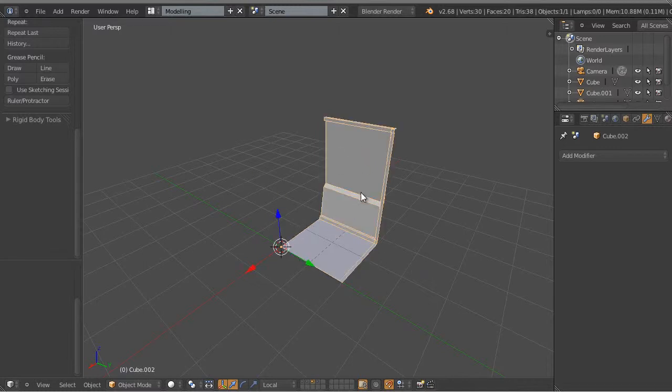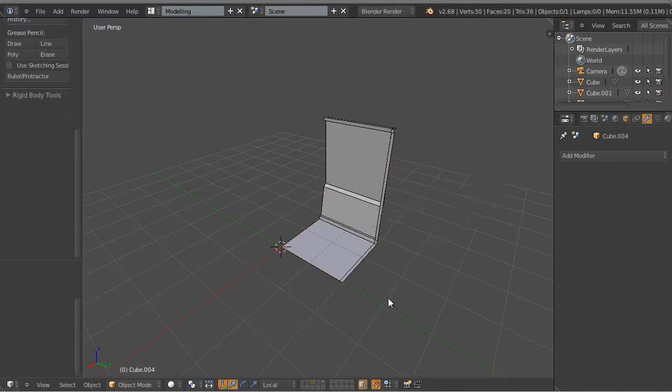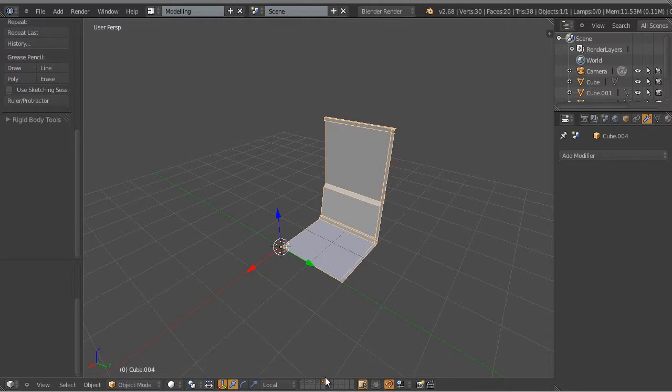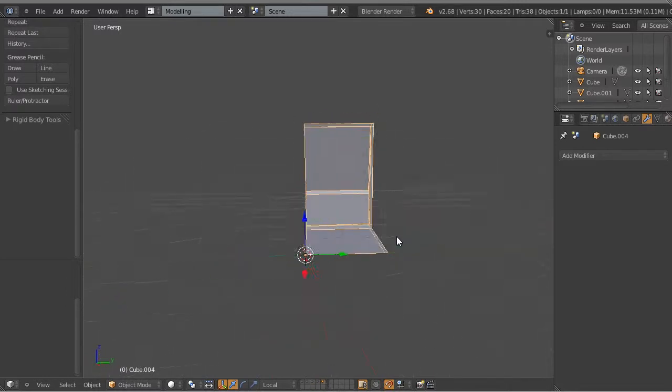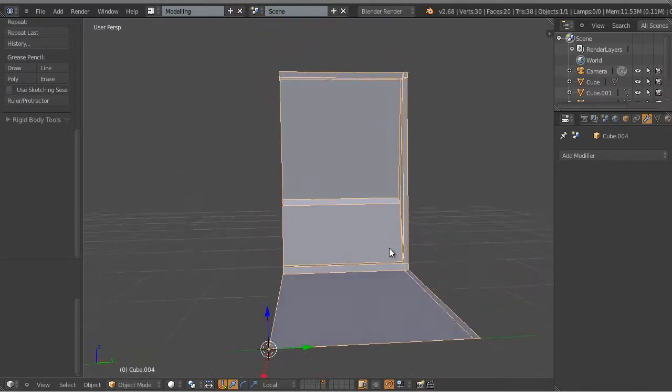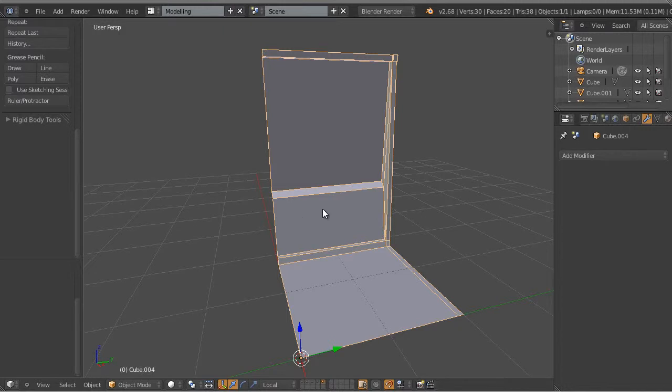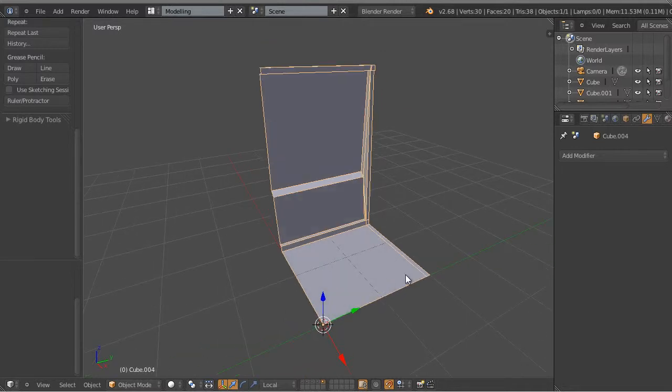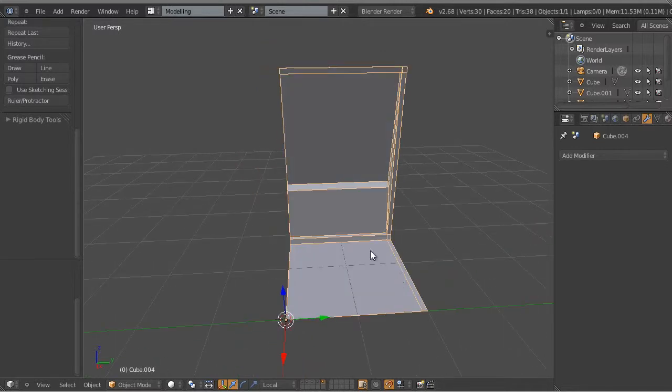So I'm going to select this quarter section here, press Ctrl D to create a duplicate, and press M on the keyboard and move it to this layer here, which is empty. I'm going to switch over to that layer and start to amend this quarter section, just to add some variation. For this section, I will add some extrusions, perhaps panels on this section of the wall, and maybe some beveling into the floor here. So let's get started.